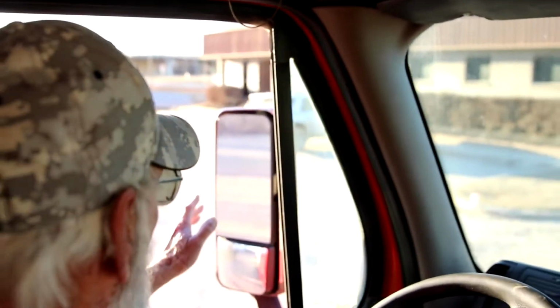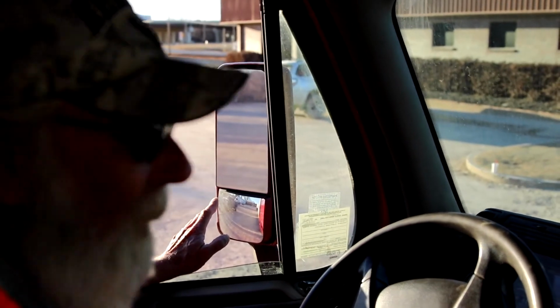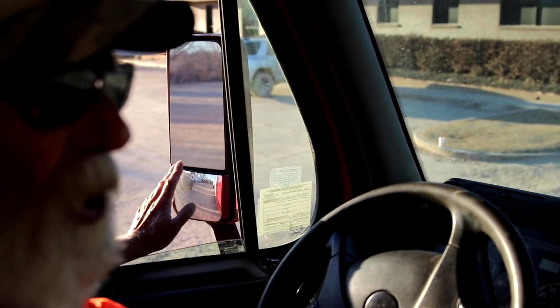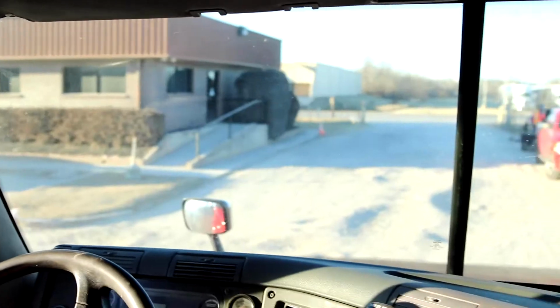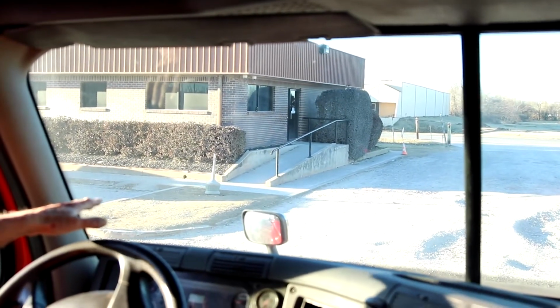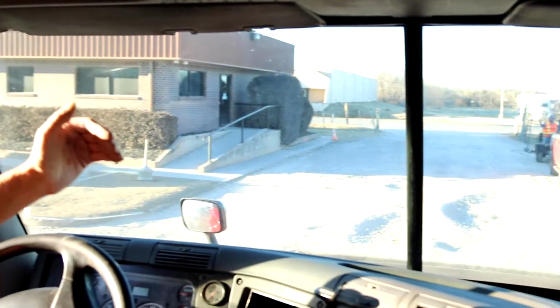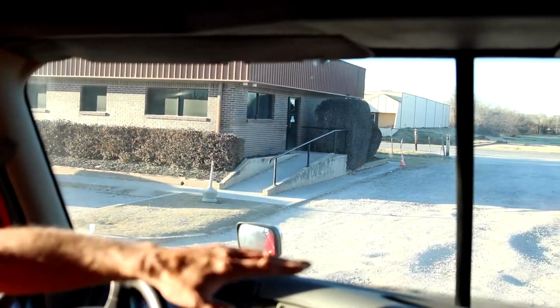Next, going to our mirrors, left and right. Mounted securely to the vehicle, not missing, damaged, or broken. No illegal stickers, clean and adjusted to me. Windshield, mounted securely to the vehicle with a weather strip. The windshields are not damaged, broken. No illegal stickers to block my view. And the seal around the windshield